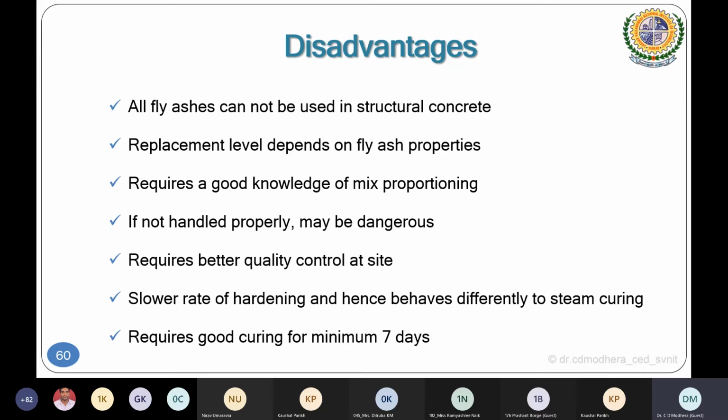30% means, while you are calculating the mix design, its other properties need to be added, right? So 100 kg is there, 30% means 30 kg, but don't take it directly. Remember, it is again with respect to the total composite, what is the resultant density. I think everything is nicely given in the calculation in IS 10262:2019. Very good calculation. M40 or M30 is given.